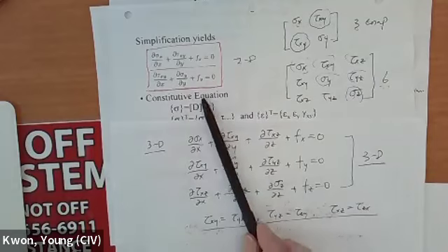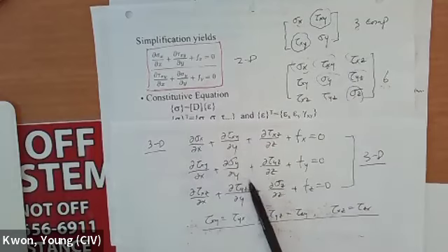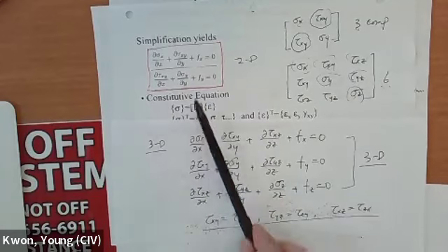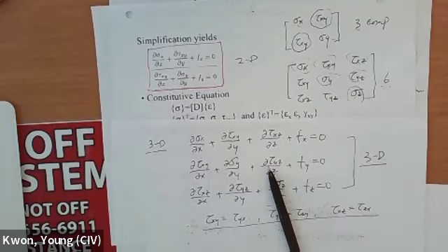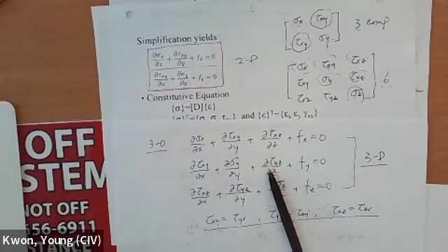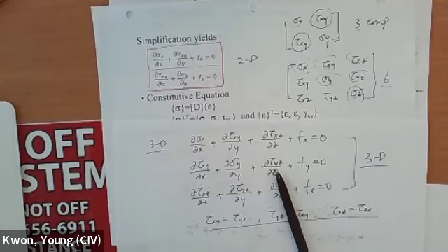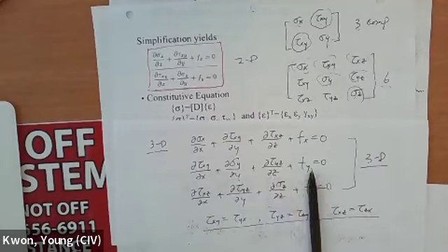Now your equilibrium equation is a differential equation, especially a partial differential equation. In beams and those elements, as you derive in undergraduate mechanics of materials or structural mechanics class, your equilibrium is just an algebraic equation: summation of force equals 0, summation of moment equals 0, right? But now in theory of elasticity, your equation of equilibrium is a partial differential equation.